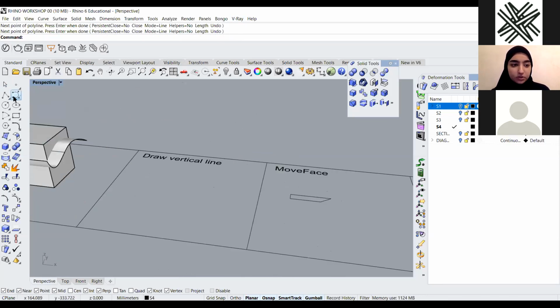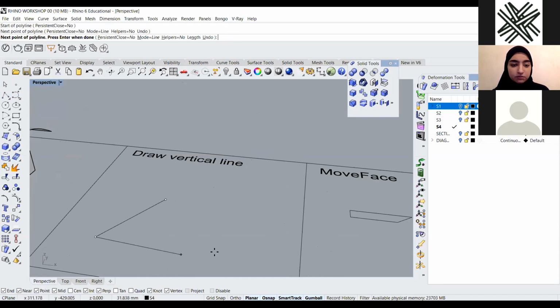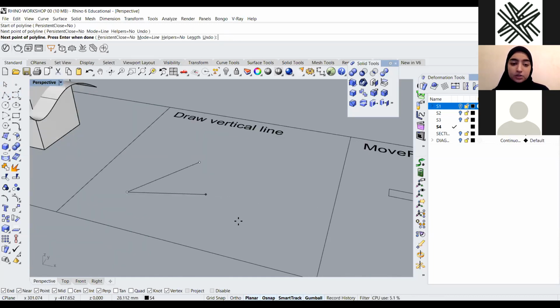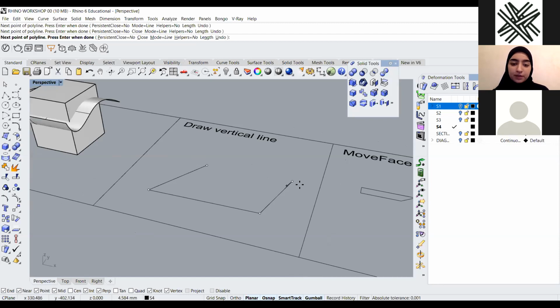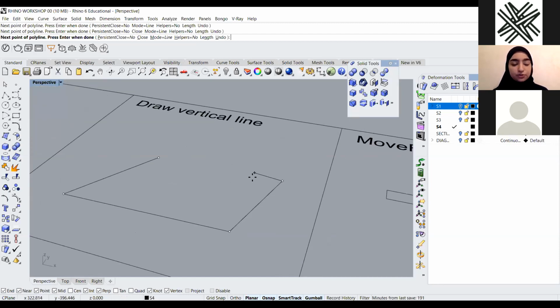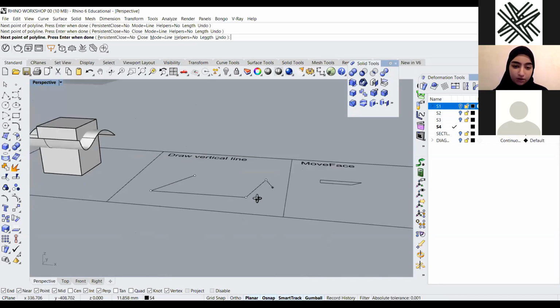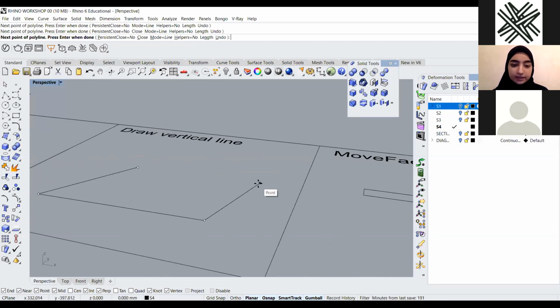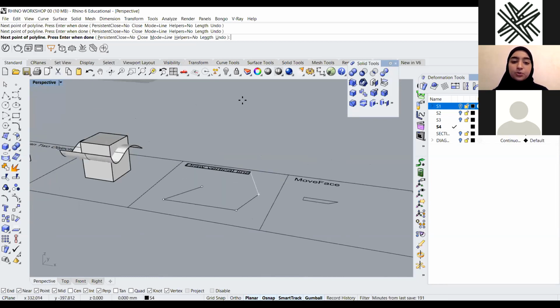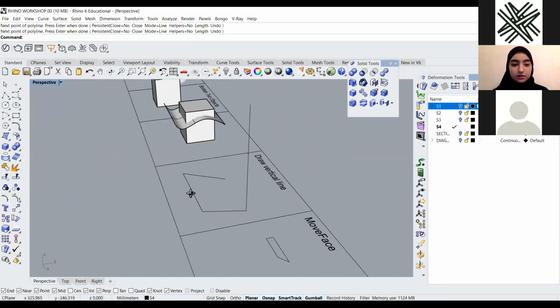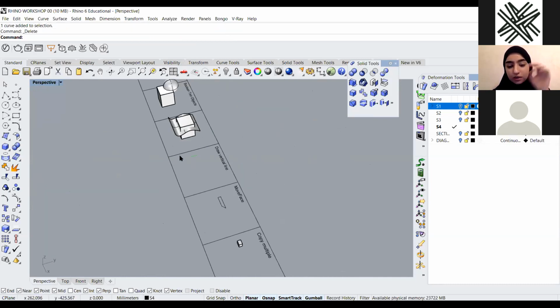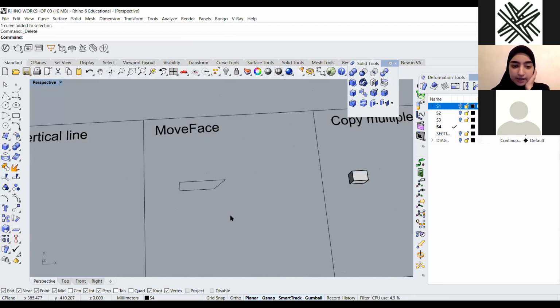Okay, so now I'm going to repeat the tip. I'm drawing a line, and then I decide to draw one vertical line to complete the curve vertically. Hold Control and click on the last point, and then you can move vertically. Okay, so that's it. Another tip.